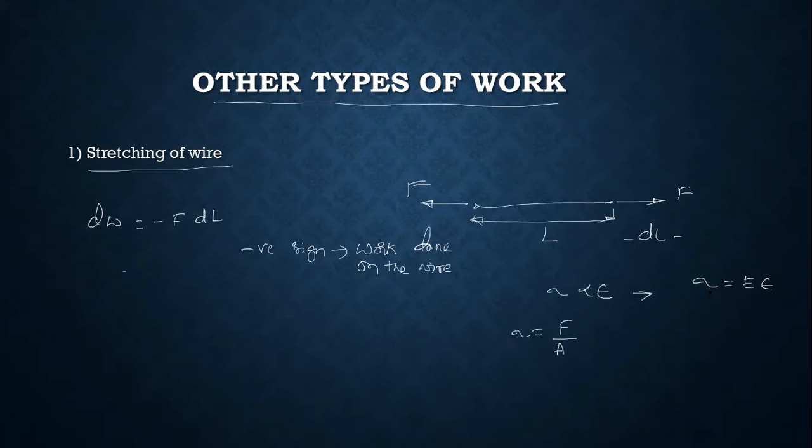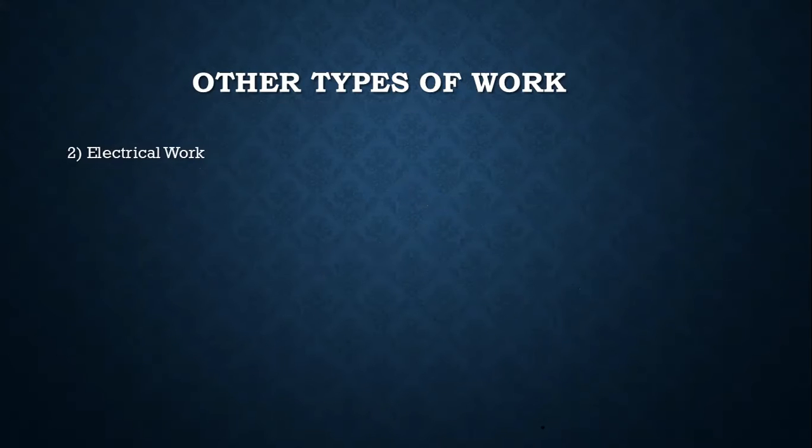Then stress can be written as E into strain. Therefore, this equation becomes E into strain equals F by A. Therefore, F is equal to E A into strain.